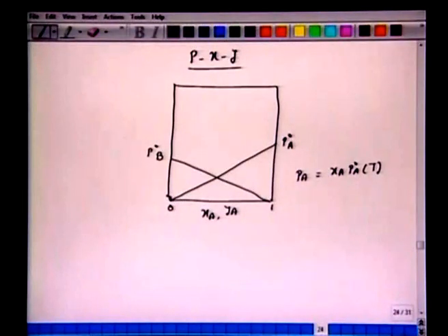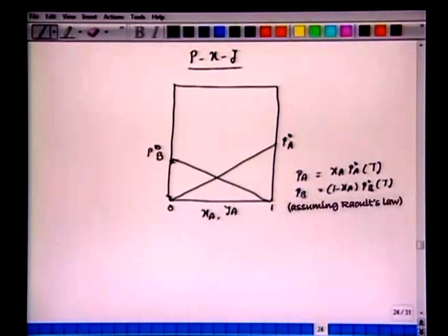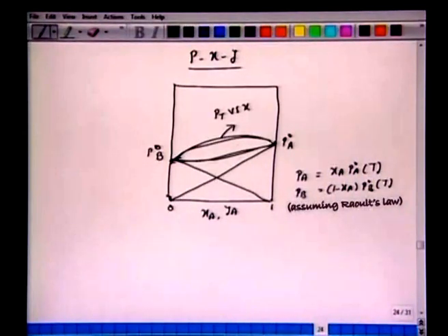So it's linear. Similarly, at x equal to 0, that means the vapor pressure of pure component B, PB would be 1 minus Xa times the vapor pressure of B. So with this one can then plot Pt versus x and Pt versus y. I leave this as an exercise. We have this Pt versus x and we have Pt versus y.